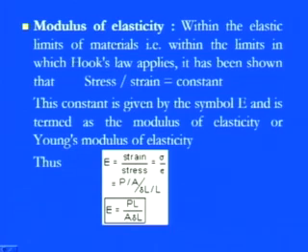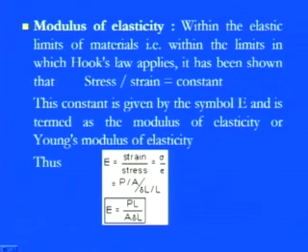We have a stress and we have a strain. When you apply the load, the stresses form within the object. At the same time, there is a change of length or diameter or any dimension, and if they are proportional, meaning that as the stress increases the strain increases, and once you set up the relation between stress and strain, it will give you a new constant. That constant is known as the modulus of elasticity, because we are considering only the elastic deformation here.